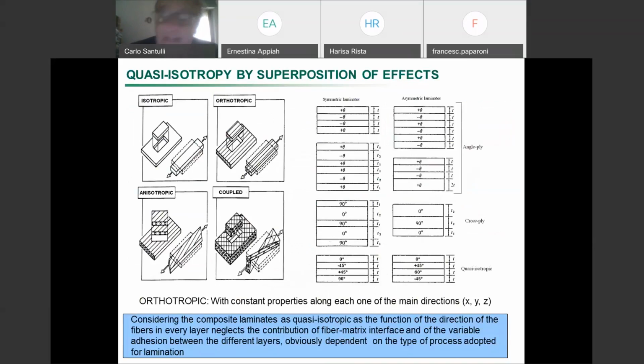My idea is always to have an isotropic material, but it's a mess. You may understand that isotropic materials are not that interesting for composites, but at least I would like to have a 2D kind of isotropic material, which stays together also in the third direction. So I might provide it with some good bonding, or even with some stitching if needed.